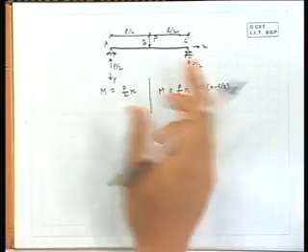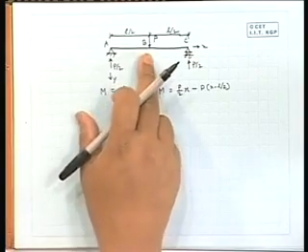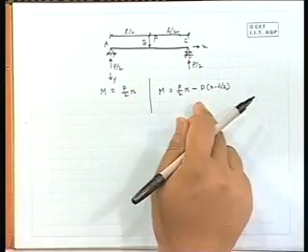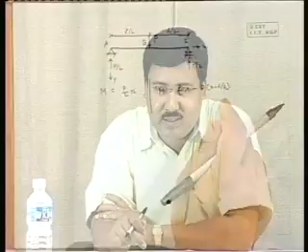Now, once we cross L by 2, the center load P will contribute something in bending moment. So, that was P into x minus L by 2. Now, after integration we got two sets of constants, left side say C1, C2, right side D1, D2.